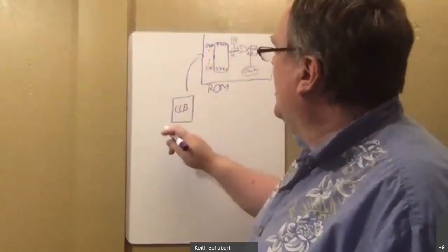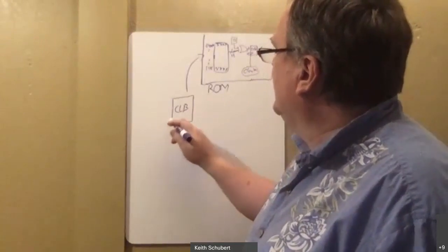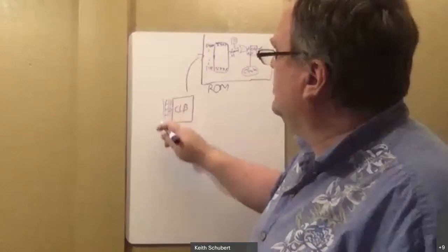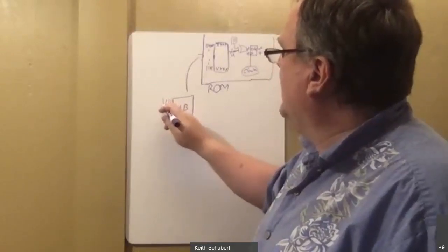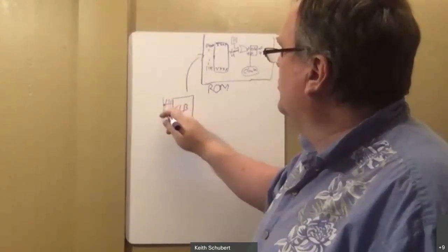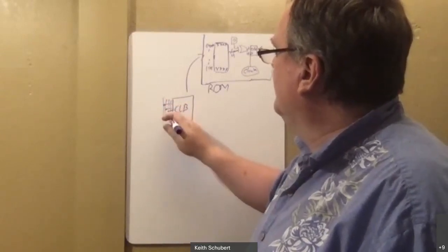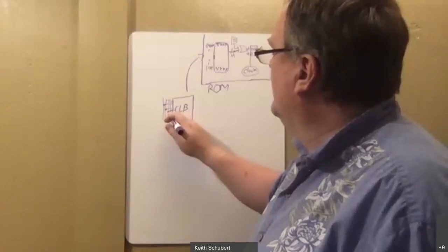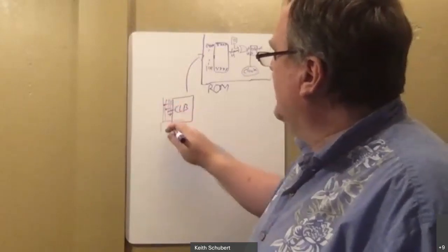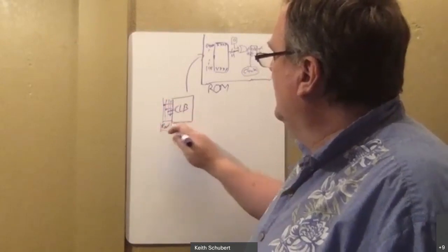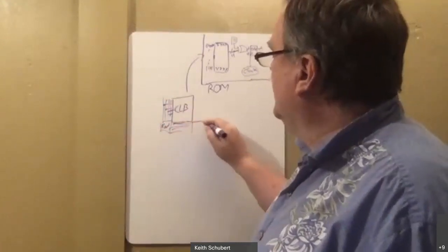Now, this combinational logic block, there's actually a whole bunch of different routings that are potential inputs. So these are wires, and they can be tapped to, do I want to read this wire for inputs? So they can select. And then you can also route. So there's routing, which selects the different areas.